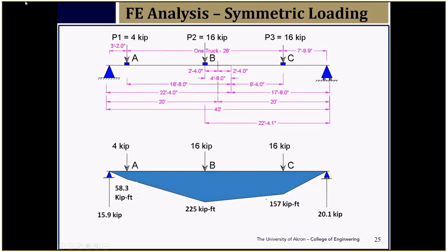This is for a 40-foot span bridge. We applied wheel loads. Of course, as long as the load is uniform over all the beams, the beams are unlikely to deflect in a differential manner, so there may not be any differential deflection. Only the wheel loads are likely to cause differential deflection, so we just focused our attention on wheel loads.